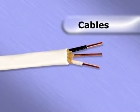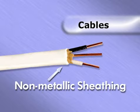Most cables used in home construction are 2 or more insulated wires encased in an outside protective coating called non-metallic sheathing. These often contain 2 or 3 wires bundled together with an additional copper ground wire.